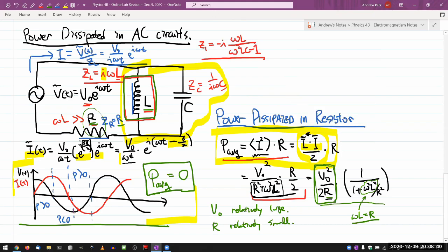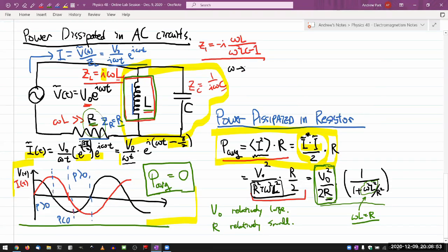If you imagine omega approaching 0, then this omega squared in the denominator goes to 0 more quickly, so the denominator looks like a minus 1. The minus cancels that, so G1, before it completely goes to 0, goes to i omega L, which is what you'd expect.